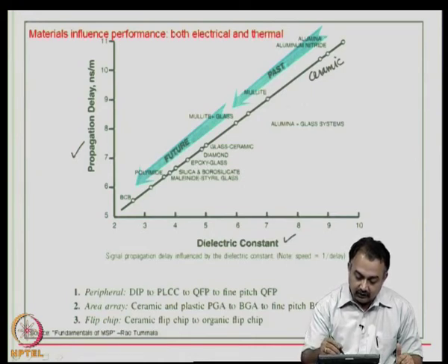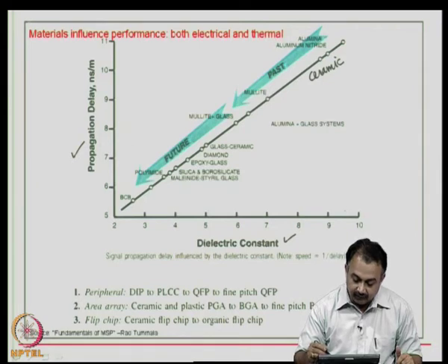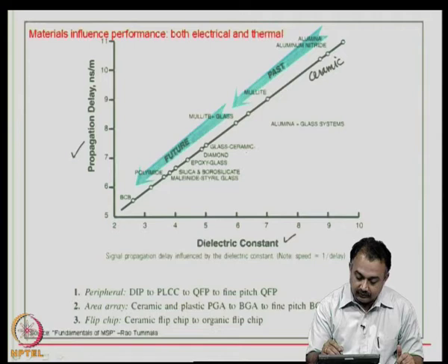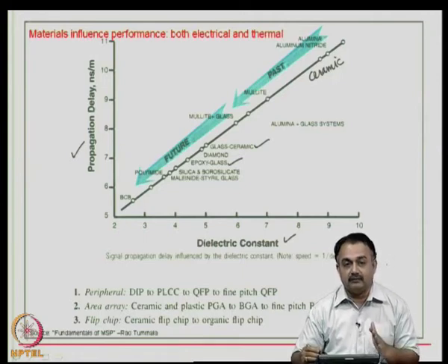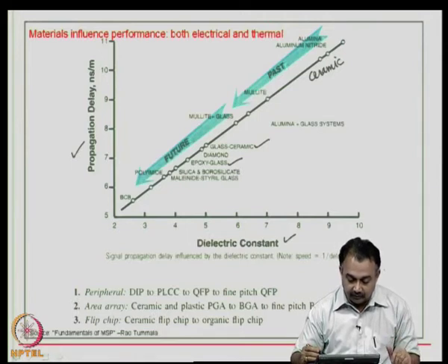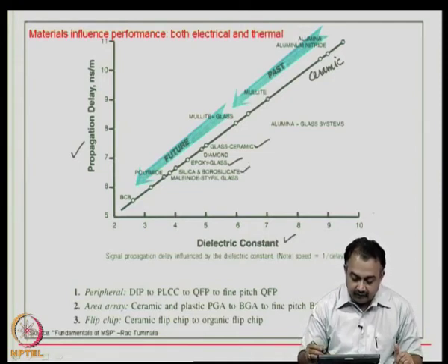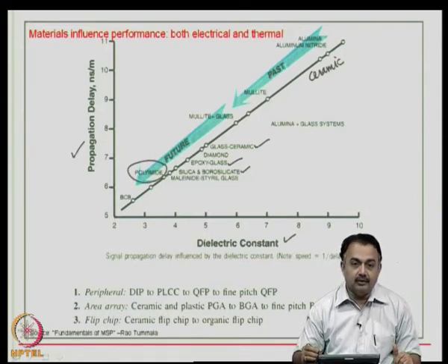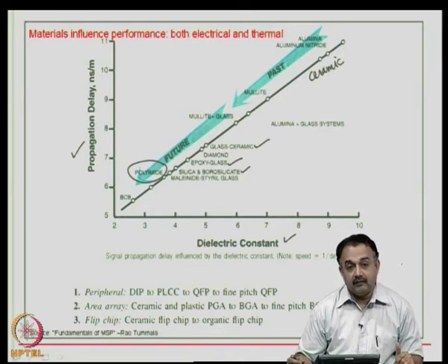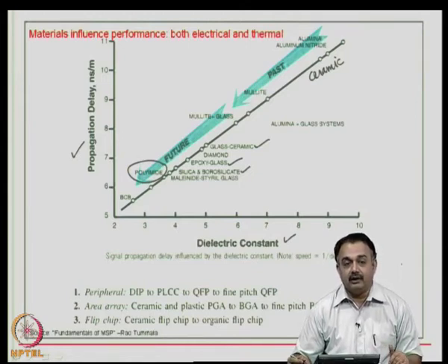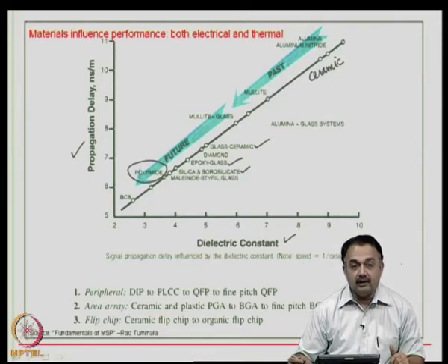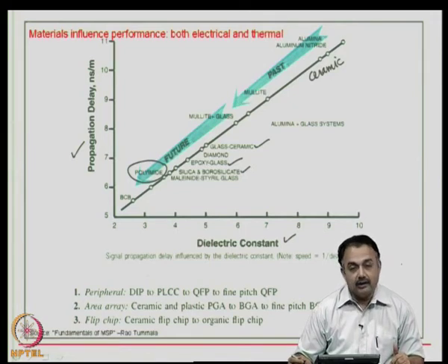As we move along in today's technologies and today's manufacturing, we have seen a lot of composites being used, for example, the glass ceramic material. Then we have the epoxy glass, whose dielectric constant varies in terms of added fillers between 3.5 to 4.2. So, we are using a lot of epoxy glass. Substrate silica is being used, borosilicate, and then polyimides have been used for high performance applications. In terms of dielectric constant, it may be superior, but if you look at other properties, for example, moisture absorption, it could have higher moisture absorption, and therefore, it could decrease the electrical performance, but at the same time it is a current material, and it could also be a future material.